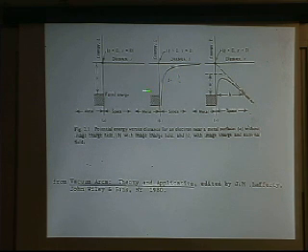But when it's coming out of the cathode, it doesn't want to come out because it's got this energy barrier, okay? Well, what happens if I apply a very high electric field? I can drop that potential well to something like this, because this is the electric field gradient that I'm going to put on there. Here I have 0 electric field gradient, but if I apply a steep electric field gradient, this is the field coming off the cathode, and essentially the energy barrier, which was equal to the work function before, equals a new smaller work function due to the electric field essentially pulling that potential well down.